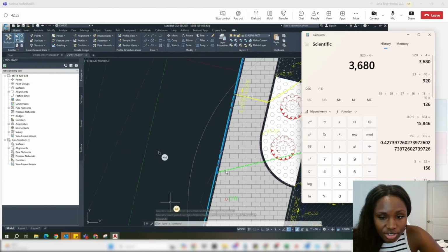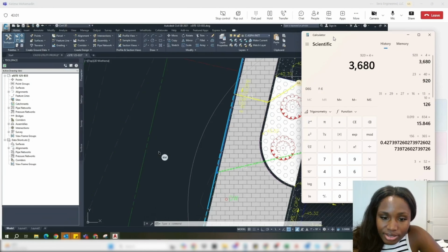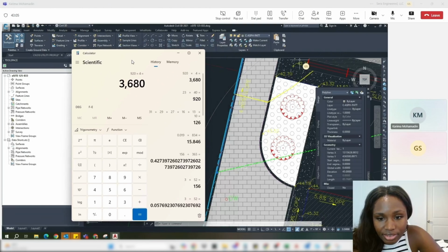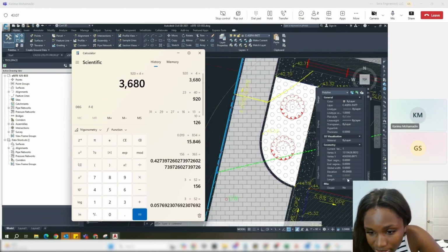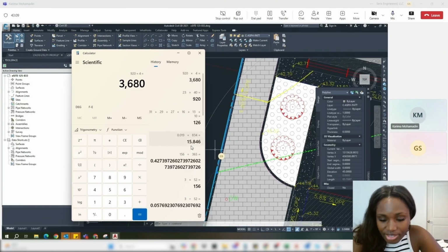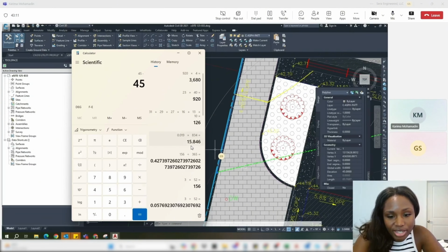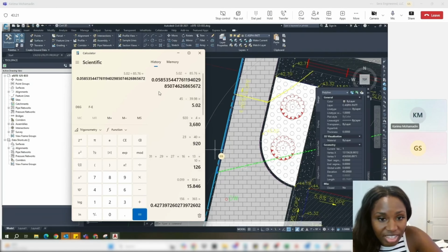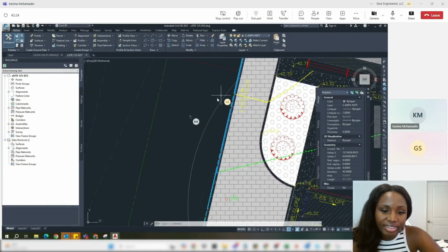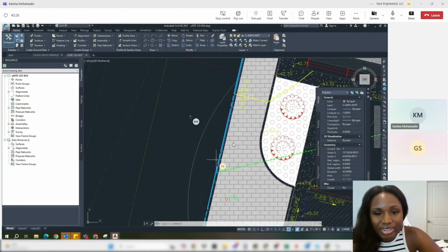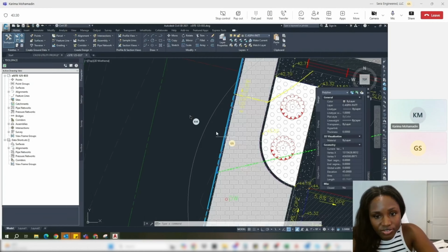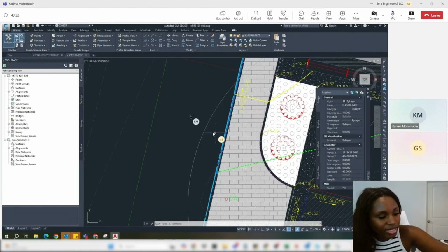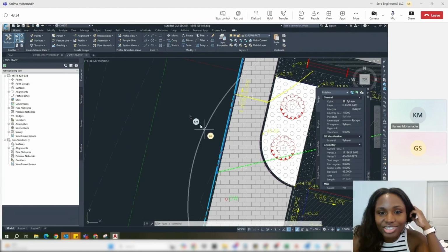With the infiltration trench, it can be up to 12%. So let's see. That's 45 minus, what is the elevation there? So, 38. So the length is 85.76. Okay, so 45. You have your calculator. I'm showing 5.8%. So we either have to add a wall along here, or the easier option is to change it to an infiltration trench, especially since all around the plans already say it's an infiltration trench.